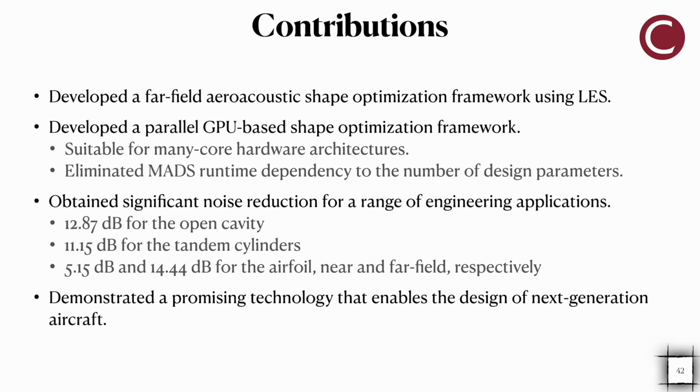The contribution of this work, in summary, was that we developed a far-field aeroacoustic shape optimization framework using high-order LES. We also developed a parallel GPU-based shape optimization framework, which is suitable for many-core hardware architectures, and also eliminates the optimization runtime dependency on the number of design parameters. We obtained significant noise reduction for a range of engineering applications, and we demonstrated a promising technology that enables the design of next generation aircraft.